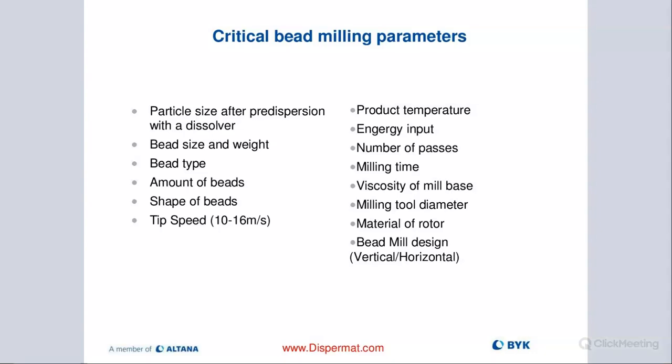And that's very important because you do not want to have discoloration of your mill base, especially when you're running very light or white colors. If you're doing blacks or dark blues or anything like that, or browns, then it's not really an issue. You can't really detect that. But if you're doing a lot of white colors, highly recommended that you use ceramic.